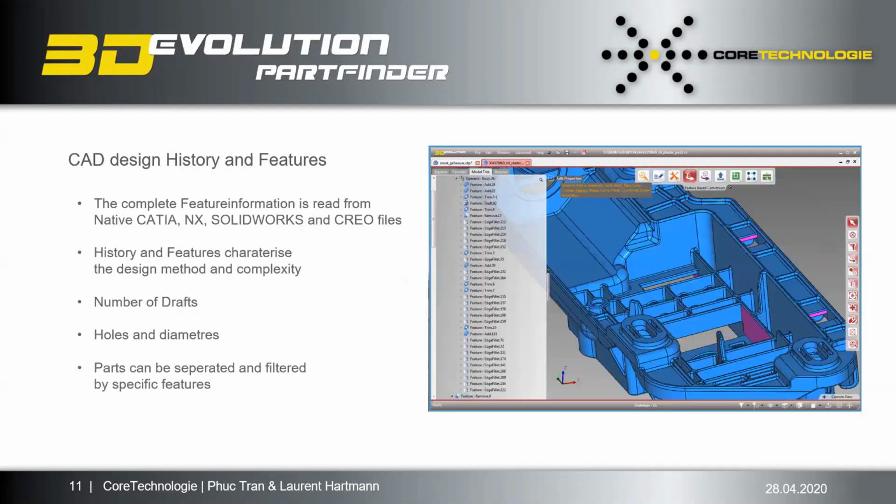And also the features history. So that means if you have a huge database of SolidWorks, CATIA, NX, Creo files, they will be opened independently of these, let me say, CAD licenses. The files will be read binary, and all the information like Boolean operations, draft, rounds, extrusions and chamfers will be read in this case.